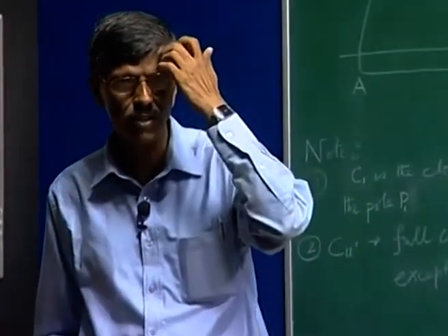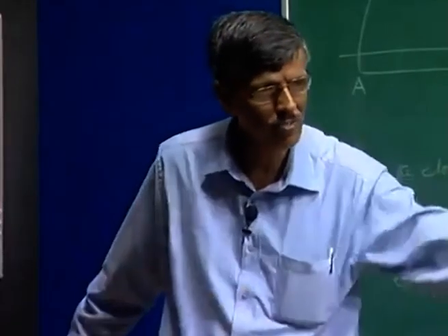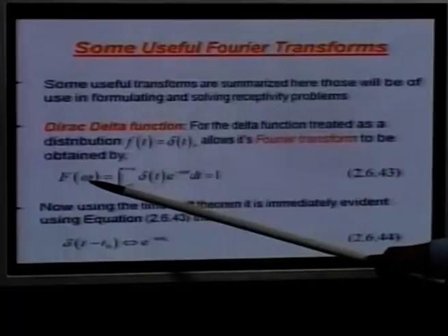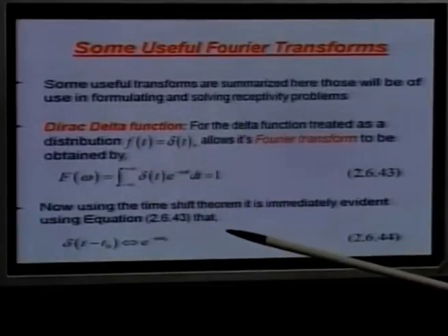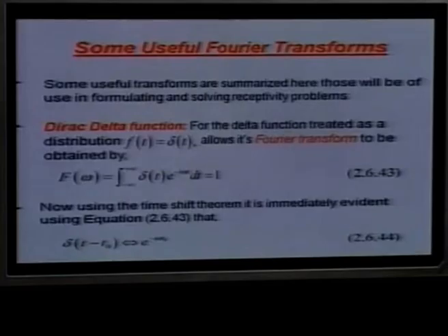So, if you are trying to look at, let us say, the natural frequency of the thing, you excite the whole system with all the frequencies and the system will pick up its natural frequency. So, that is why we said in the last class also that impulse response would be preferable over frequency response.